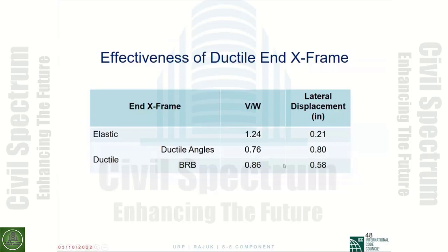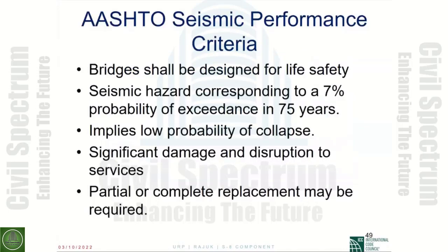So the lateral force, once you have a yielding element, you will limit the base shear, but you will have a larger displacement. And that's what you want to make sure of, that you are allowing for this kind of displacement.